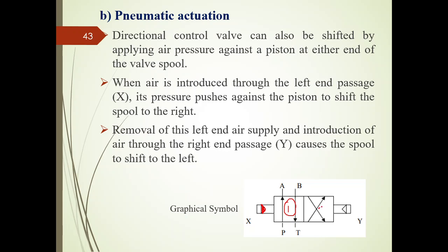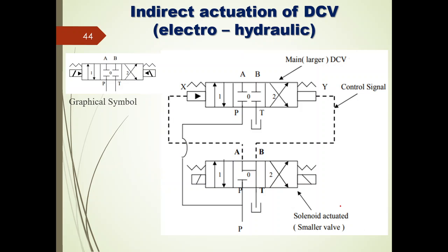And if you want to actuate the second position, then you need to apply the pneumatic air pressure to the Y section, right? So the Y passage. This is in the case of pneumatic actuation.